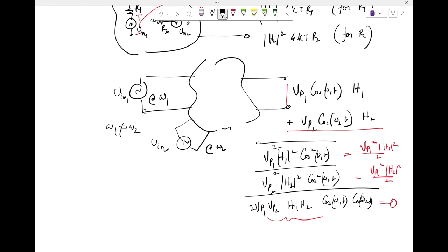Doesn't make sense? So I'll talk about it in a way that probably makes sense. Let me finish this thought. The key thing that I'm pointing out here is that when you have multiple noise sources at play, all you have to do is find out the power spectral density for each of these individual cases and add them up. You don't have to bother about the cross terms.